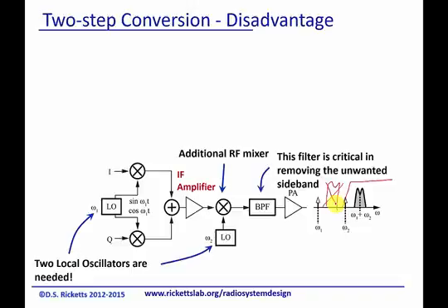A lot of cell phones now use surface acoustic wave filters, SAW. What they do is they basically take an electrical signal and launch it on a piezoelectric substrate in a way that it only transmits a very narrow band of frequencies. The reason we do this is these filters have extremely low insertion loss and extremely sharp filtering, so it's worth it to go into a specific technology just for these specialized filters.